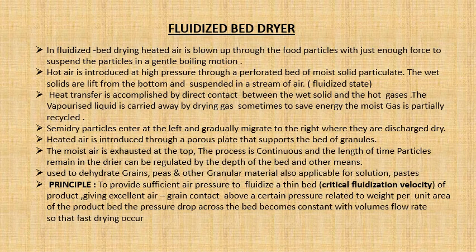Next, it is the fluidized bed dryer. In fluidized bed drying, heated air is blown up through the food particles with enough force to suspend the particles in a gentle boiling motion. Hot air is introduced at high pressure through the perforated bed of moist solid particles. The wet solids are lifted from the bottom and suspended in a stream of air, and this is called the fluidized state. Heat transfer is accomplished by direct contact between the wet solid and the hot gas. So the vaporized liquid is carried away by the drying gas.